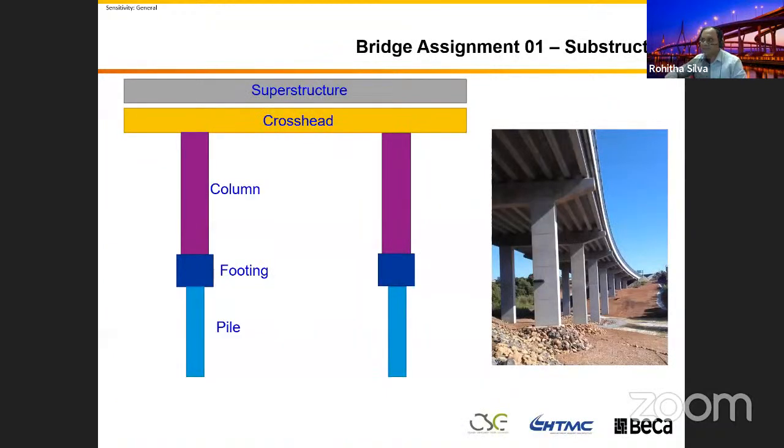So then we're going to select the substructure. Because we're going to have one bridge, 26.1 meter width. We have an individual girder, 11 or 12, and then the 11 or 12 sitting on bearing. Then the substructure is quite obvious, it's a portal frame.